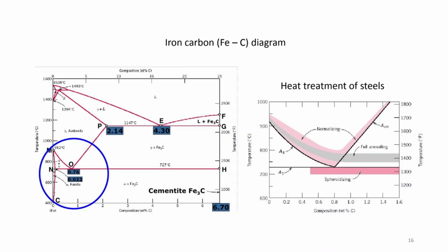So this is the iron carbon diagram. Here it is shown up to Fe3C, and the temperatures are corresponding to the iron carbide diagram. Okay, because Fe3C is forming. If it would have been graphite formation, then it would have been iron carbon diagram, and those require more equilibrium conditions compared to this.